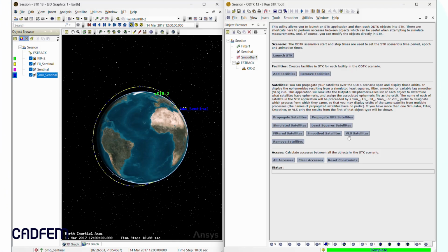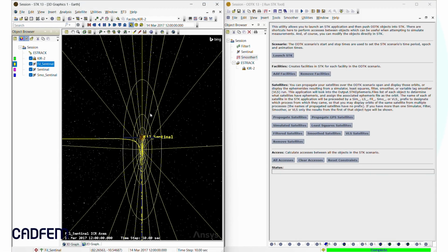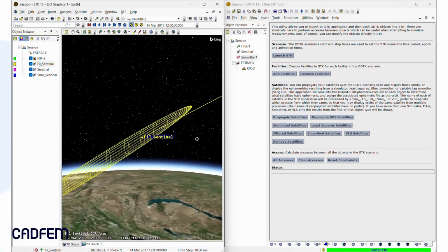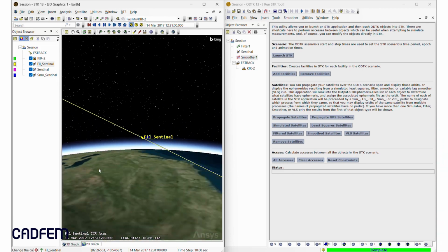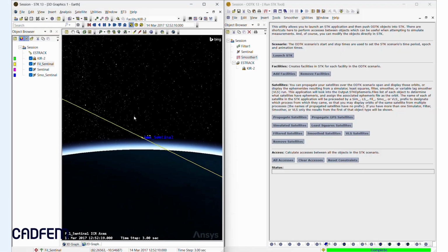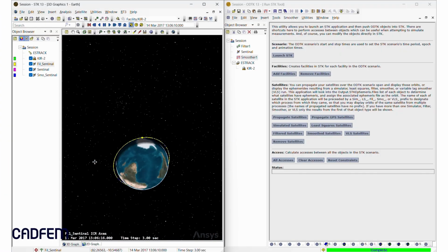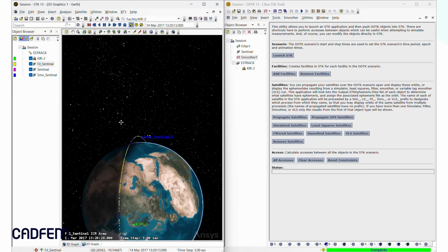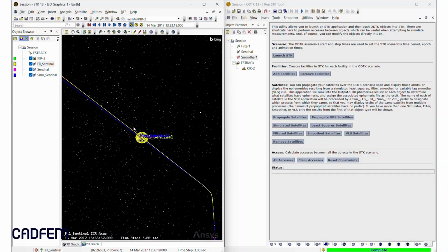Because the ephemeris files contain covariance data, STK can render 3D uncertainty ellipsoids that represent surfaces of equal probability density. The probability level is set to 95%, matching the sigma scale used in the ODTK analysis, ensuring consistency between estimation and visualization. When we view both satellites together, the smoother ellipsoid is clearly smaller than the filter-only solution, reflecting reduced uncertainty after bidirectional processing. By visually comparing the filtered and smoothed states, we confirm covariance improvement and overall solution consistency.